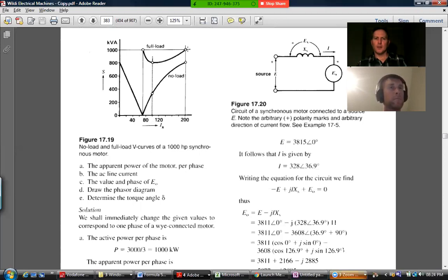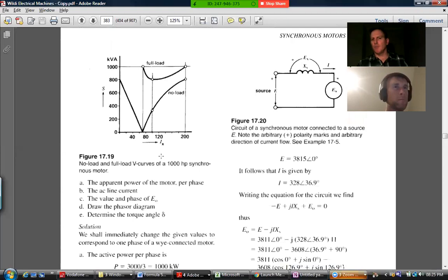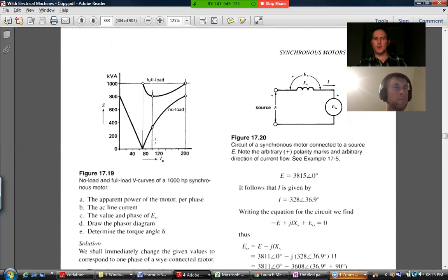and what is this telling us? It's telling us that, this is real power here. Real power. So the real power is somewhat affected by whether you're overexciting it or underexciting it to some degree. The real power is affected on this curve, but not as much as the reactive power if you overexcite or underexcite. So yeah, don't worry too much about those V curves.